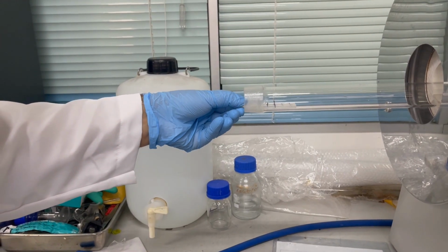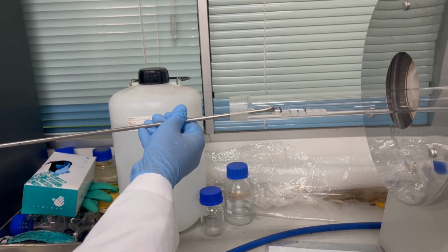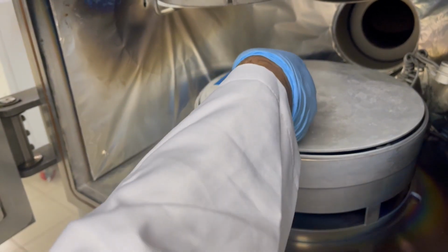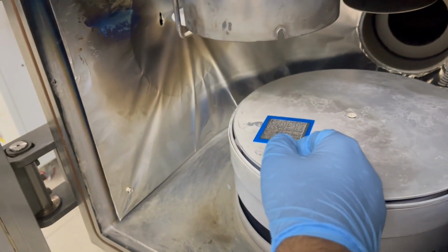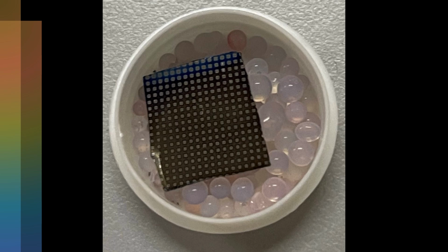The samarium metal is then simultaneously oxidized and nitrided in a tube furnace at high temperature using nitrous oxide gas. Samarium oxide is thus formed. Aluminum metal electrodes are deposited on top to complete the MIS structure. Thus, the complete MIS device is obtained.